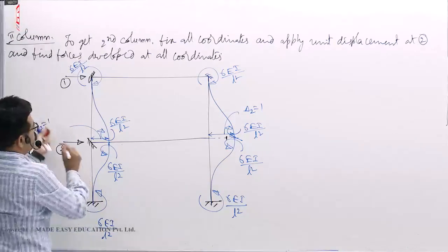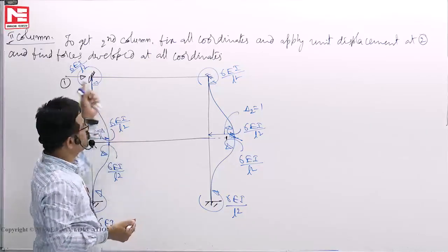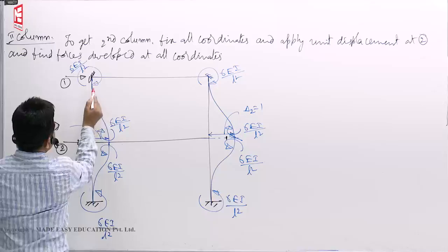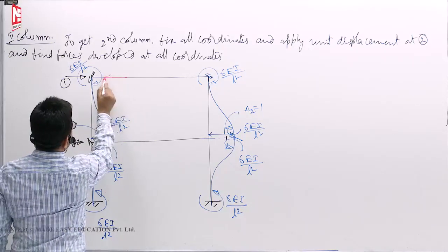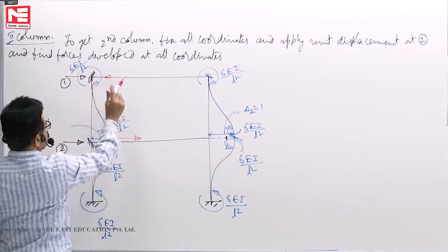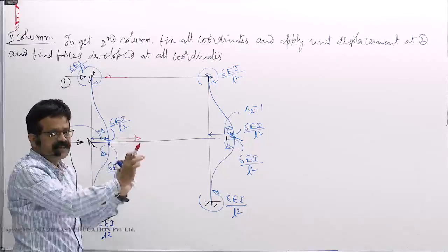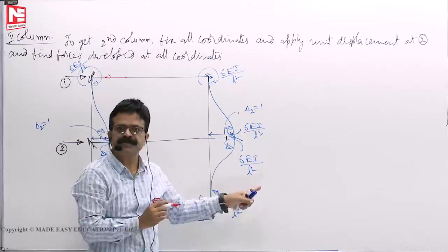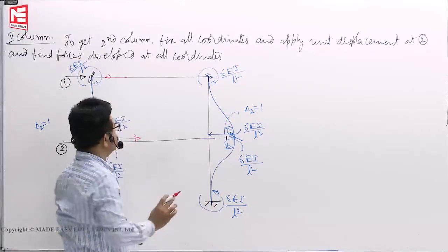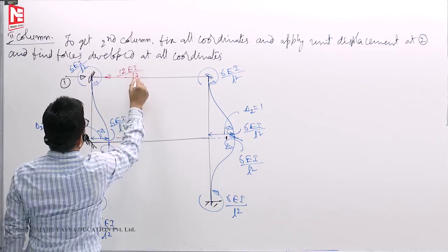Now moment forces. We are not interested in the moments, but without finding moments we don't know the force. We forgot, let us say, then both of them are clockwise. So here anti-clockwise couple will form like this. If this is clockwise, anti-clockwise couple, individual free body diagrams we can take and the forces can be clubbed, because principle of superposition you can apply. These deformations are not large. Okay. So this is now 12 EI by L cube.